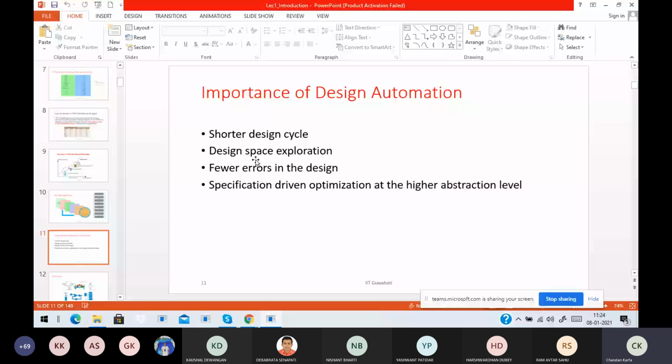For all these things, if you want to develop a gate level design or an RTL level design, you have to develop them from scratch. There is no interrelation between them. So you have to have a different design for different goals. But with high-level synthesis, I have the same C code, and I can utilize the high-level synthesis software tool, which, with the target objective, will design an RTL automatically from the same specification.